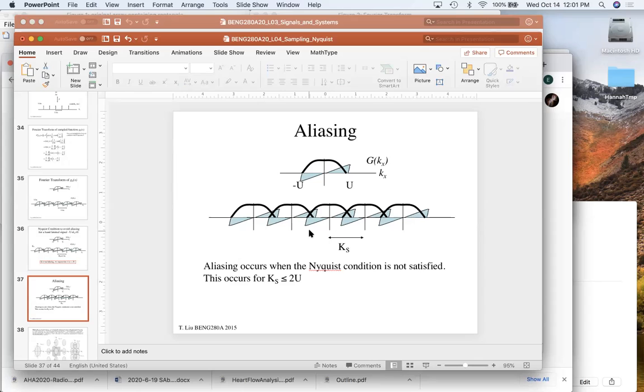The only way really to increase your sampling rate in CT a little bit is to take one view and then shift the sampling grid by a half sample spacing and take another view, so you're jittering between two views.